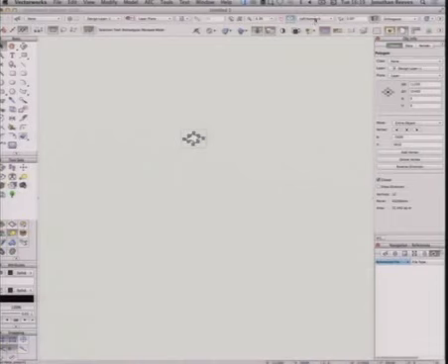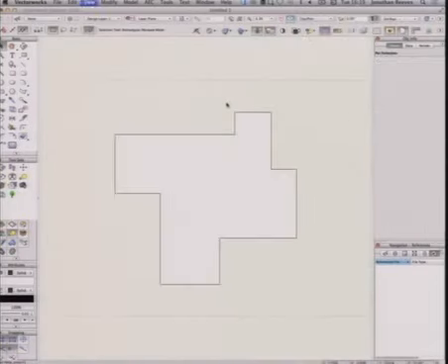When I'm ready, later on, I can translate that origin to be up in Sheffield, or I can do it via referencing onto the site model. I don't need to do it now. I can model nice and easily. So my tip is, make life easier for yourself. Don't model at a funny angle. Don't model with a funny origin just because that happens to be where somebody else imported the survey file. Make it easy for yourself and model in the middle of the paper.